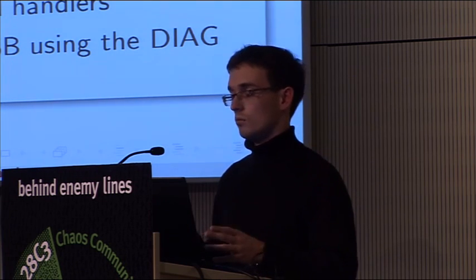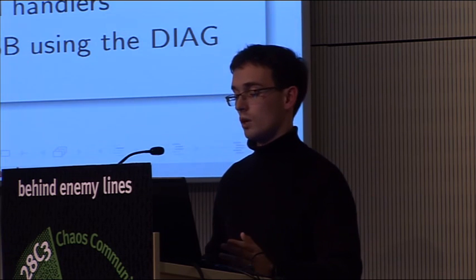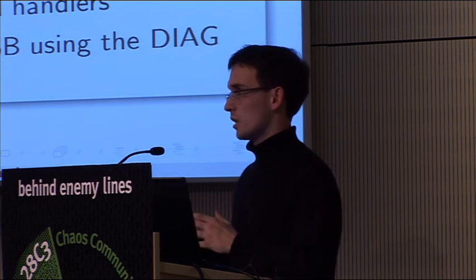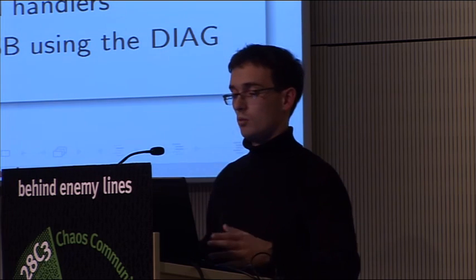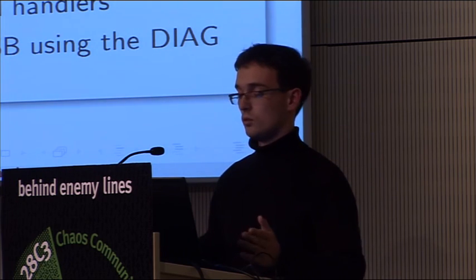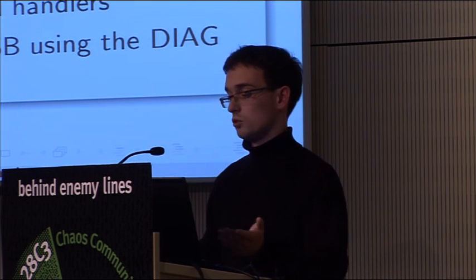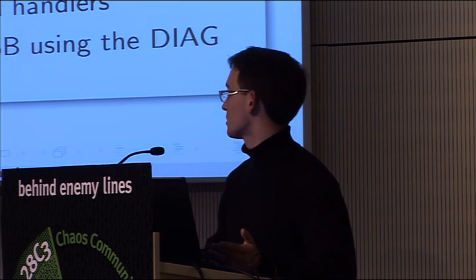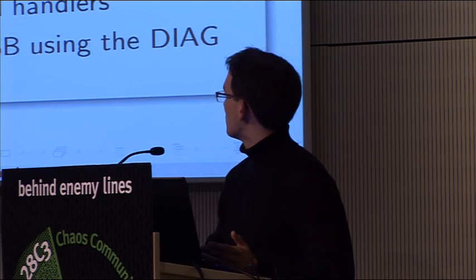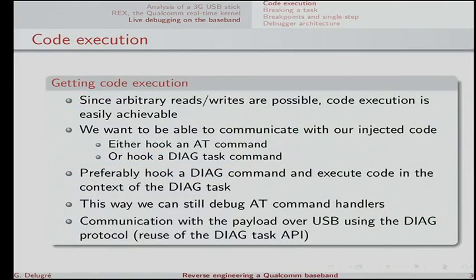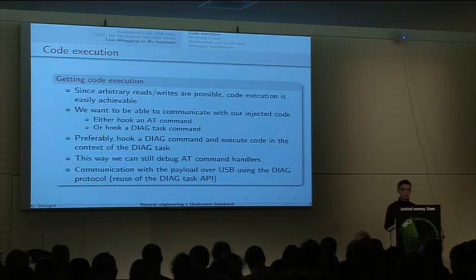Optionally, I could create another task in the system and be able to debug every task, but it's not very important because the diagnostic task is not a critical task in the system. I'm basically just reusing the features of the diagnostic task and using its own API to communicate with the payload over USB on the emulated serial port.